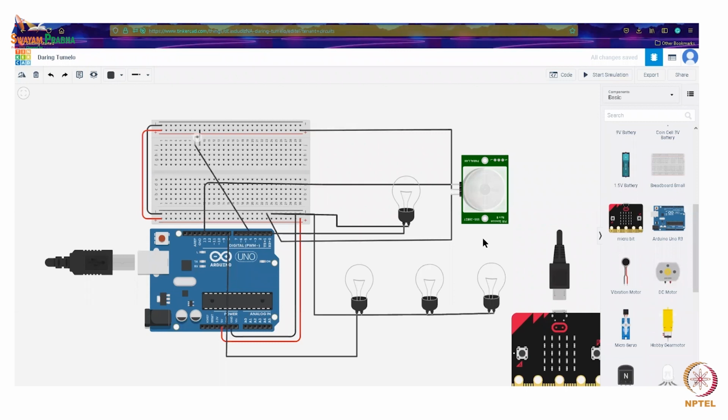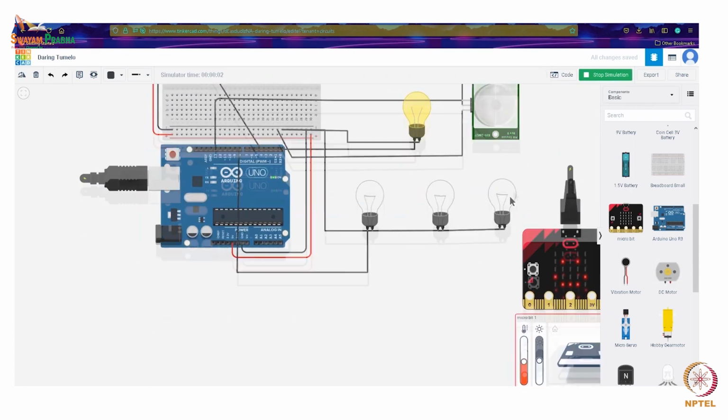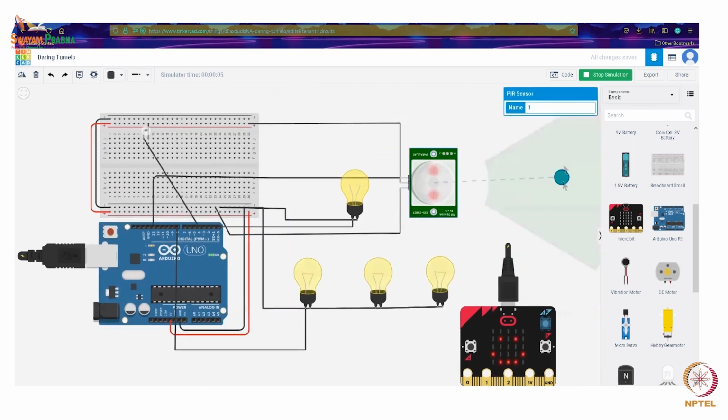Actually, we didn't use the Arduino exactly. Okay, I'll tell you the exact system that we used. We used 5 PIR modules. We modified the circuitry and made them run on batteries for about 30 days, so the modules are standalone. We placed them at 5 different spots near the entrance. As you see in this simulation as well, there is a view angle. The PIR only works for a certain angle, and our PIR modules had a viewing angle of 45 degrees. We placed them in such a way that they observe anyone who comes into the room.